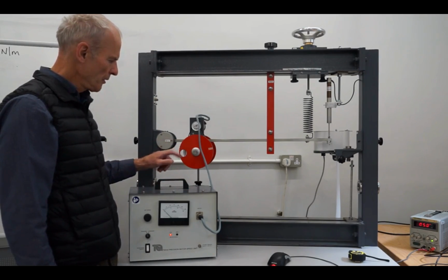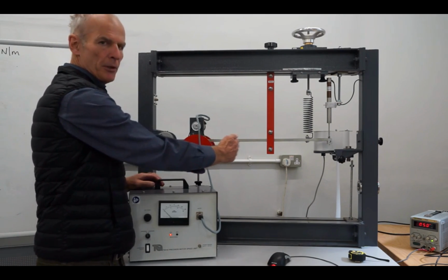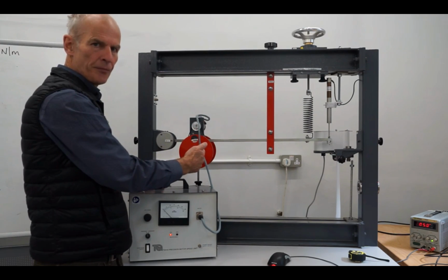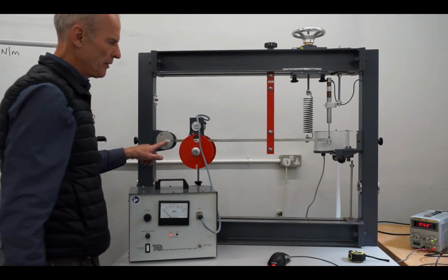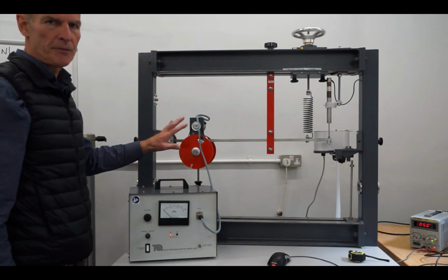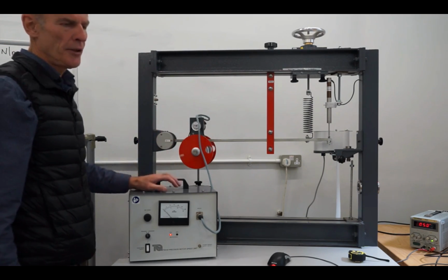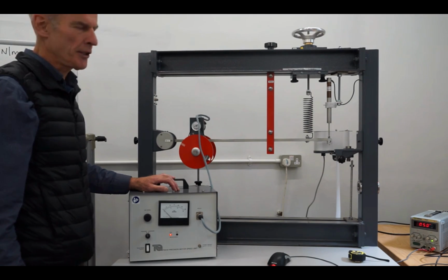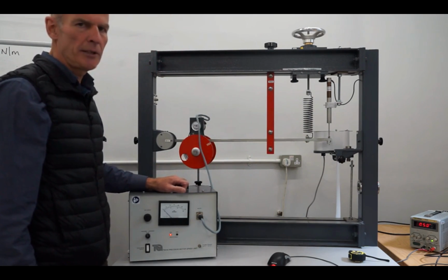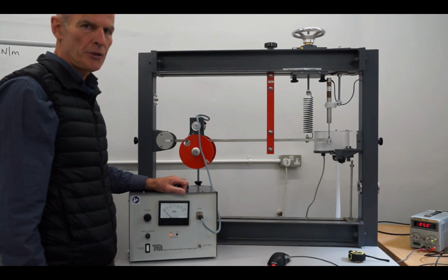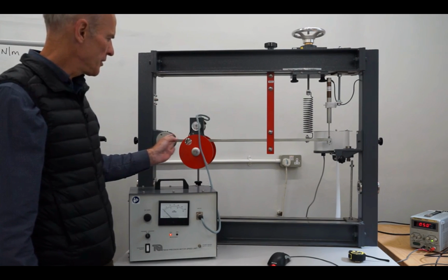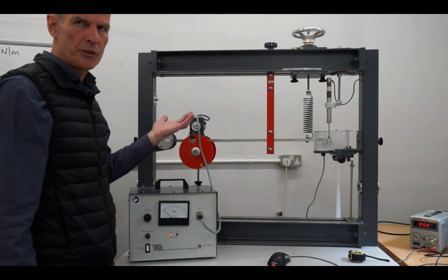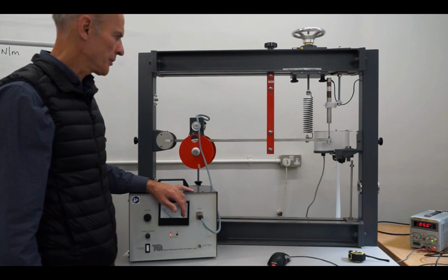Okay, so for this position, the whole mass is moved towards the axis here, which means that we've actually changed the inertia of the system. So the reason we've done that is we changed that distance L1. So remember, the total moment of inertia is now changed, and what this means is that the natural frequency will change. Remember that natural frequency is essentially K L squared, which is the stiffness K times the length L squared, divided by I, being the second moment of mass. So if you lower I, and by changing this distance, if you make that smaller, you change I and make that smaller. Therefore, if you make I smaller, the natural frequency goes up. And so essentially this is how this system will work.